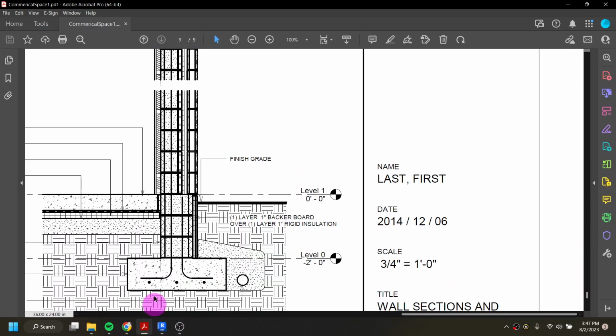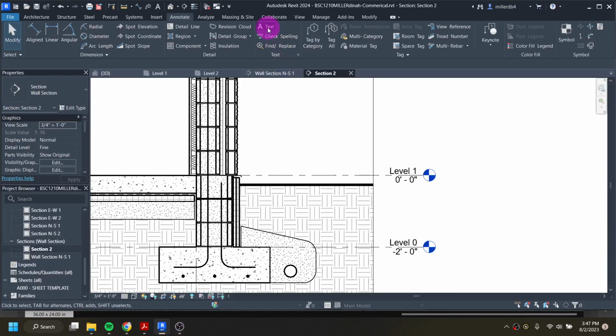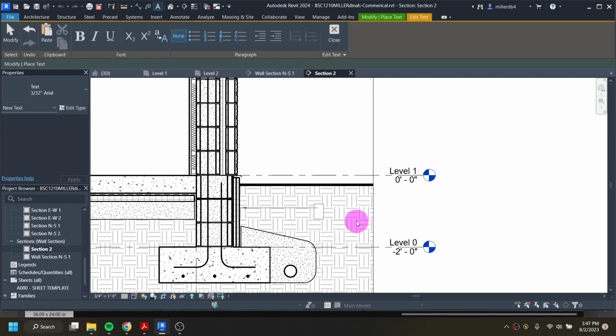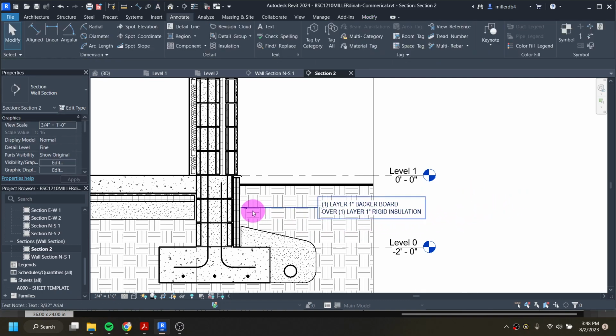And as a refresher for all of these text boxes, what we would do is we can even, oh no, I thought I would be able to highlight that text and copy it. Okay, looks like I sort of can. So I can Control C to copy this text. I can go into Revit, say I want to use the text box. I'll just have one arrowhead, point it to where I want it to go. Where do I want the text box? And then Control V to paste. So at least this way I don't have to type out each and every one of those. So that could be a nicer way to get them in there.